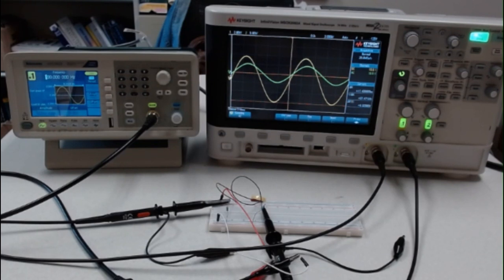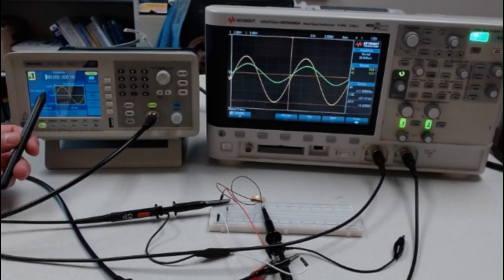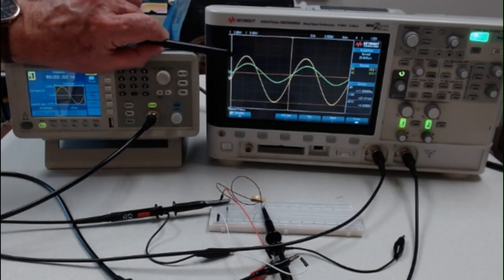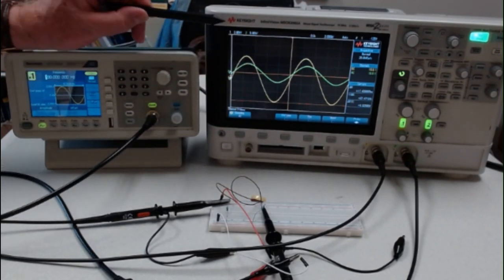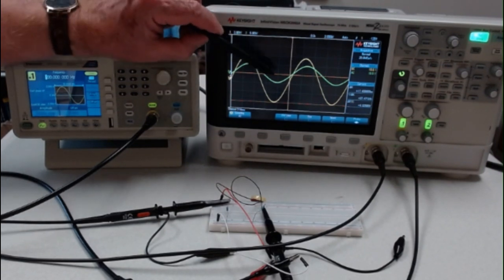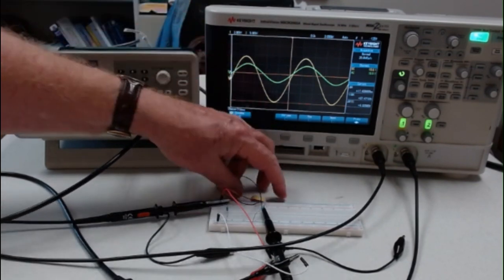This time we're looking at a waveform of an input, and this is our input waveform right here. It's a sine wave, and I can change the frequency of the sine wave, and right now it's at 100 hertz. It says set the input waveform at 10 volts peak to peak. We have 2 volts per division. Here's our 0 point. It's almost up to 5 divisions, so that's 10 volts peak to peak. So we've got our input set at 10 volts peak to peak, and we can measure the amplitude peak to peak of our output.